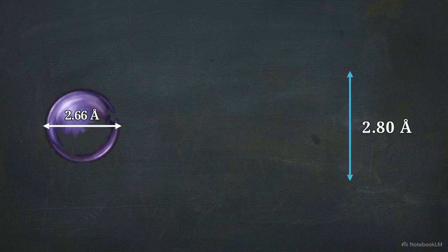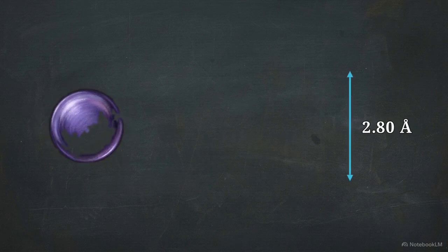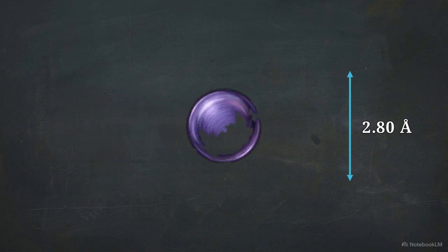Potassium's effectiveness relies on exact molecular dimensions. In swelling clays, the interlayer lattice gap measures exactly 2.80 angstroms. With a 2.66 angstrom diameter, the potassium ion slots precisely into that gap. This triggers the upper and lower clay lattice layers to physically snap together and lock.